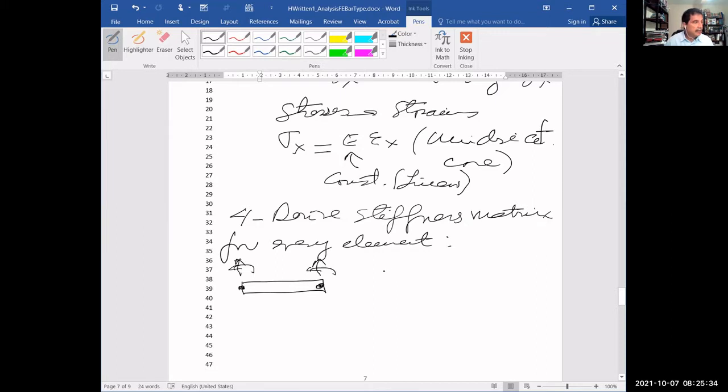And in our case, we're going to be using one method in chapters 2 and 3, what we call the direct method. And using equilibrium, we're going to transform this into this. A matrix, what we call like that. And that's going to be multiplied by the displacements. For example, it's going to be D1Y, this is Y. Then with one phi 1Z, D2Y, and phi 2Z. Okay, so you can see that these are the displacement and rotations of the two joints which define this element.